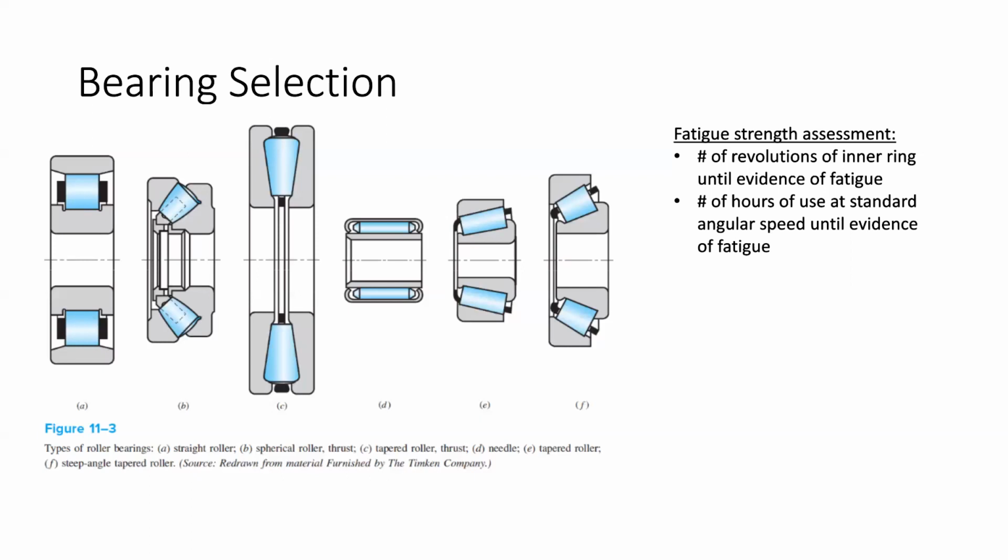So let's say I took a sphere and I were to take a plate and push against that sphere. For the initial part, I have a stress concentration basically at a point on the sphere, right? And I have an infinite stress, even though I have a finite force that I'm pushing on it with the plate. As I push further and further, that sphere is going to deform and the contact area changes from a point to a circle of area. So that circle of area is now distributing my stress across the bearing. And the interesting thing is that the stiffness of that joint is actually changing as I do that. So the harder I push, the lower the pressure, even though it's the same amount of force, right? So the stiffness of the system actually goes up as you deform it more.